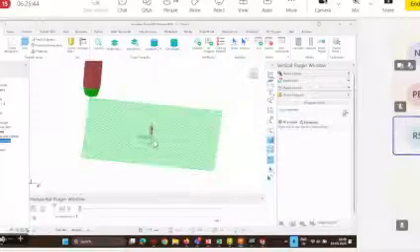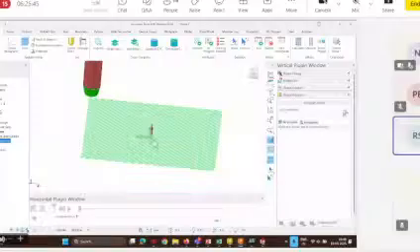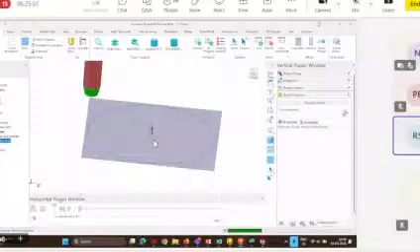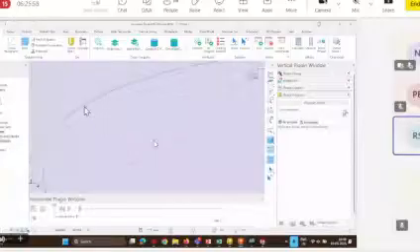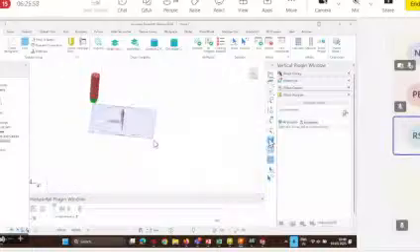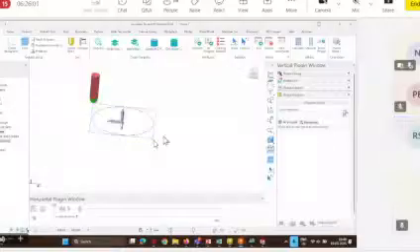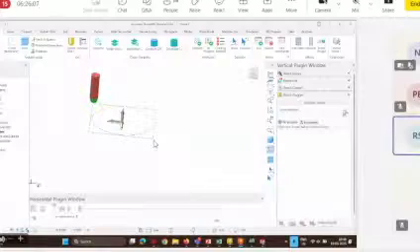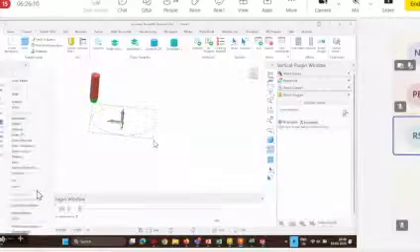To switch off the toolpath view, you can just click on this bulb or you can deactivate it. And now if I select this curve, the variable block also I can hide from here. And then we create a pattern and insert this curve into this pattern. And now if you copy this pattern and paste as the boundary,